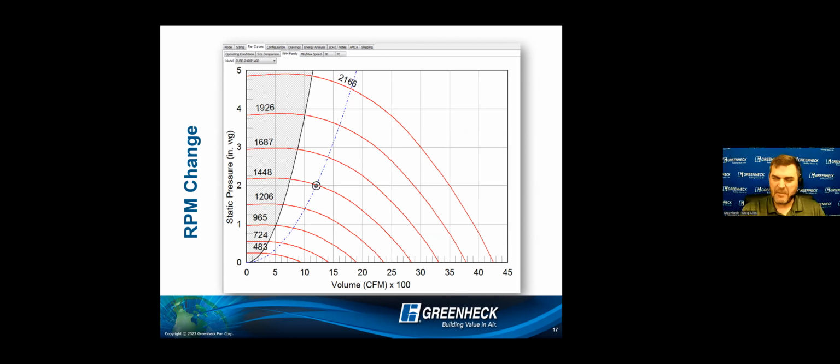Again, if you think back to where we started, the math behind the fan curves, this is literally my first and second fan laws shown graphically, right? At different RPMs, as I change RPM, my CFM will change 1-to-1. And the curve of that system resistance line, that blue line, is going to be an exponential curve because it changes to the square.